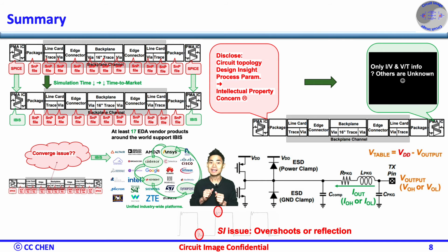Again, IBIS models are behavioral models which describe the electrical parameters as seen at their terminals. It's a black box model which reveals no internal information, unlike the SPICE model which discloses everything. Fourth, the IBIS may include signal integrity specs like input logic threshold, overshoot, etc. The last one is that the IBIS is backward compatible with models created under previous IBIS standards, and that's sustainable.